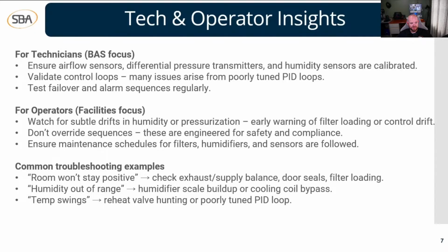The next thing here is going to be insights for operators. This has more of a facility style focus. So operators, when you're walking through your buildings, working on things, watch for subtle drifts in humidity or pressurization. This is early warning of filter loading or control drift.